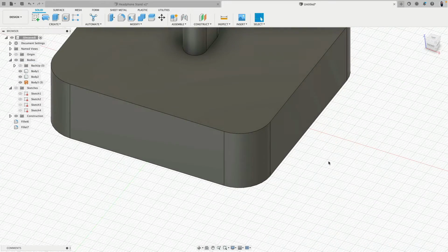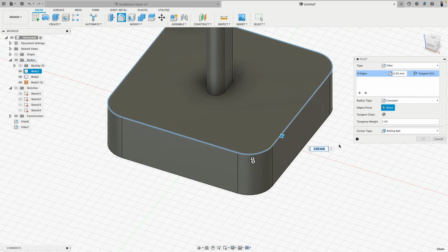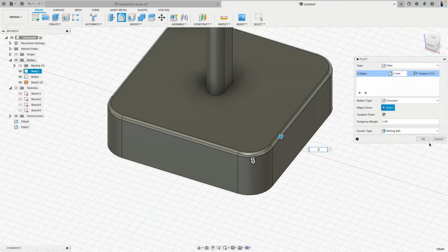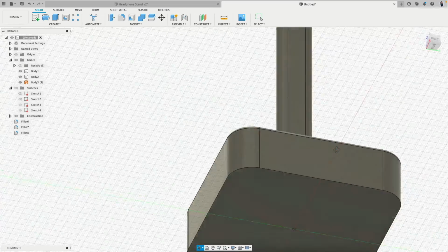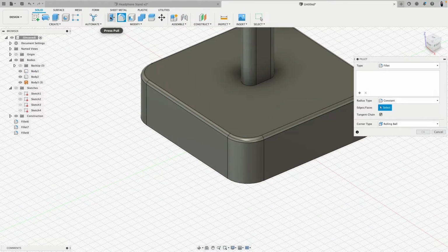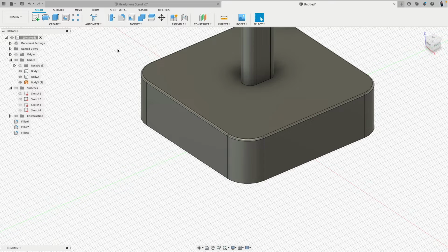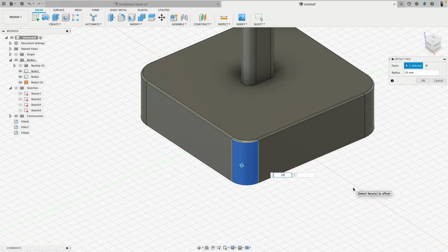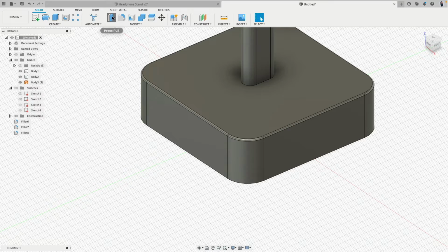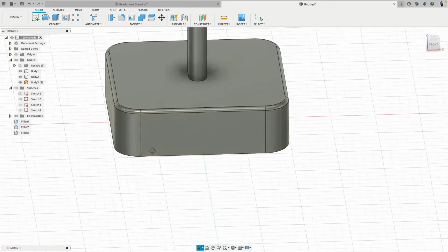Okay, very nice. This is now a very sharp corner. Let's go ahead, fillet this a second time, 2 millimeters. Look at this. This looks beautiful. Now, because we are in direct modeling, we can actually go ahead and say push and pull this to 1 millimeter. You see how this updated it. What about this goes, instead of 14, 10 millimeters? You see how everything else moves with it. So this is actually a really nice tool and workflow to so freely adjust everything.